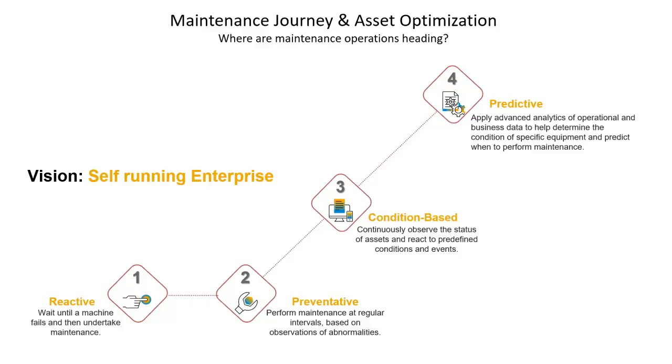They are waiting till the machine fails. Some have moved further, graduated to do the preventive. So performance maintenance at regular intervals based upon the manufacturer recommendation and so forth. And then there are very few who have moved from preventive to the condition based.